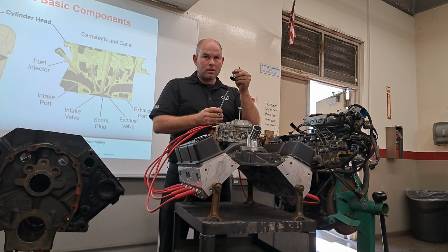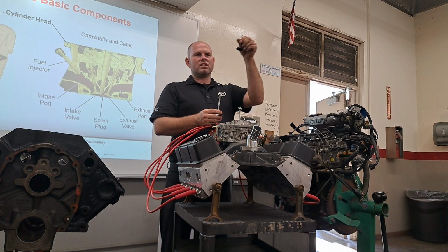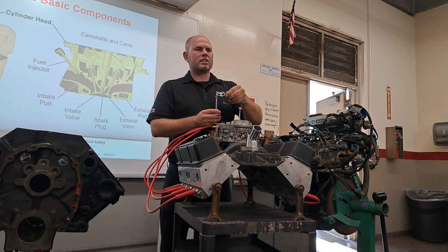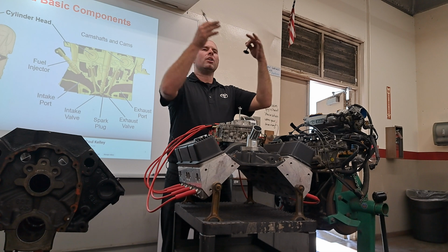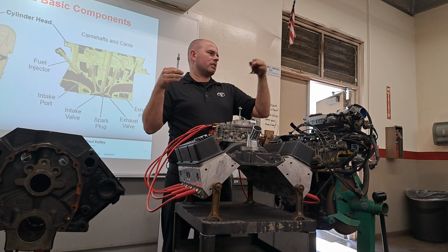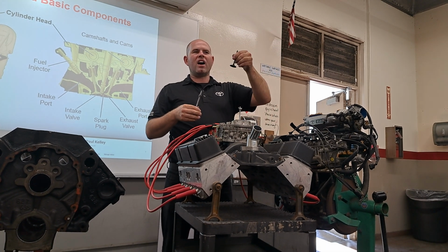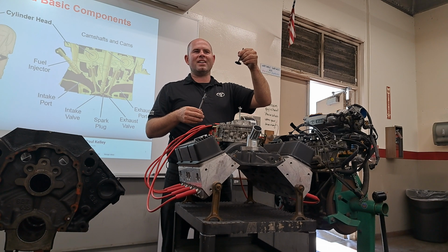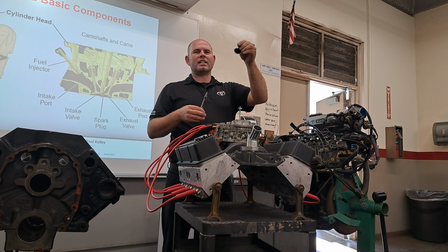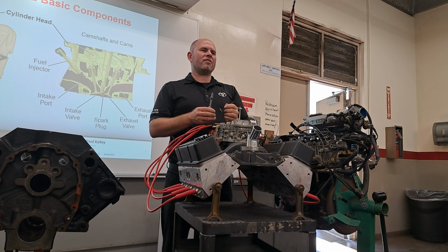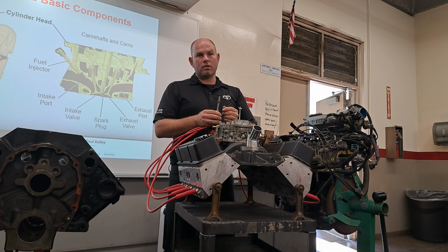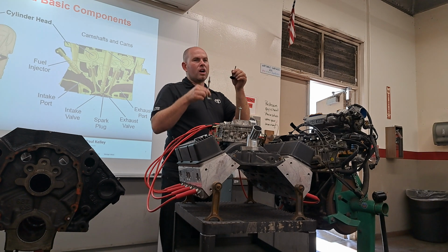Let me explain. This valve gets hot. When it touches the head, it passes its heat off into the head, and the head passes it into coolant and cools it. So if this valve is open, is it ever touching the head? It's never cooling. That's how you burn a valve. You burn a valve, now you got a misfire, now you really need to redo the thing. Make sense? So when we talk valve adjustment, that's maintenance type of stuff.